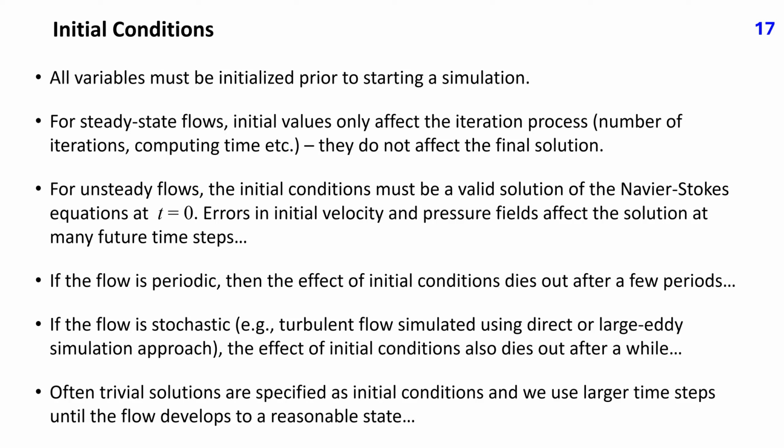If the flow is periodic, then the effect of initial conditions dies out after a few periods and does not affect future solutions. If the flow is stochastic, for example, turbulent flow simulated using the direct or large eddy simulation approach, the effect of initial conditions also dies out after a while. Often, trivial solutions like constant velocity and pressure are specified as initial solutions, and we use larger time steps until the flow develops to a reasonable state.